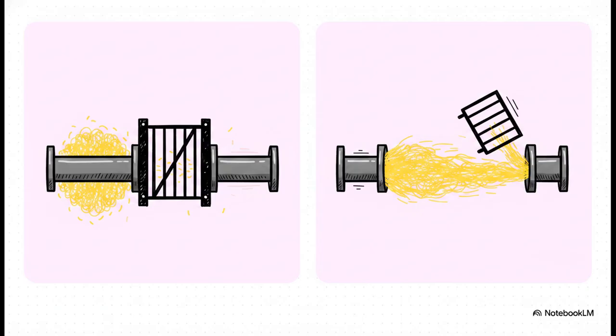If we keep the pressure, the drain voltage, constant, and slowly lift our gate, we see zero flow until we hit that threshold voltage. Once we pass it, boom, the current suddenly starts shooting up because we are creating the channel. Conversely, if we keep the gate voltage constantly high, meaning the channel already exists, and we turn up the drain voltage, the current rises immediately. There's no threshold to wait for because the electrons are already there, ready to move.